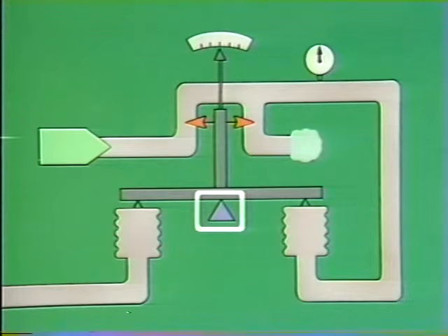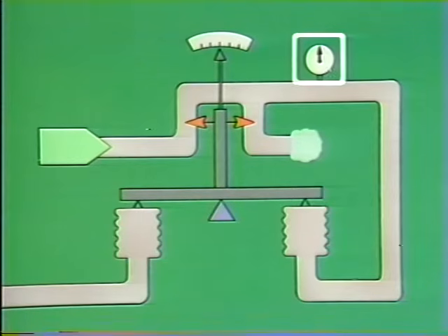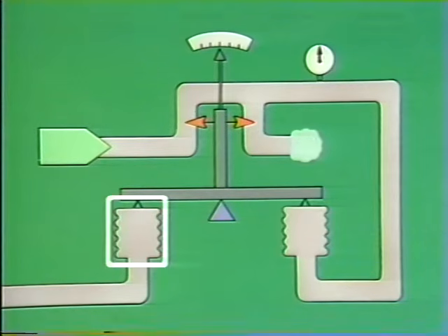The pivot in this example is centered exactly between the input and balancing bellows. So when this instrument is balanced, the back pressure, as indicated on the gauge, is equal to the input pressure. Well, that's basically how a self-balancing instrument works. When an unknown input is applied, an error is detected and the output is automatically changed until balance is restored. By calculating or measuring the change in the output of a pneumatic instrument, we can determine how much the input changed.